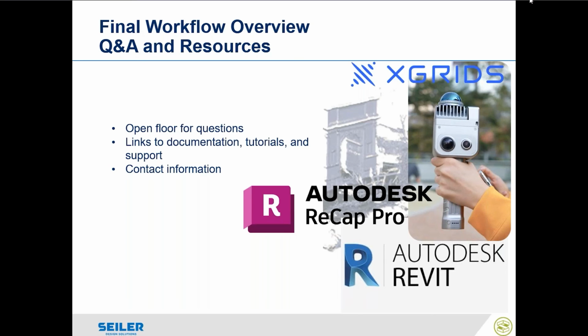Now the software is set up to remove those transient objects when you're processing. So as the slam scanning is going through, as you're seeing people in the raw data, when you get to the process, most of them will be removed. You can dial it down, so there's like a narrow tunnel. Let's say I'm putting this through a manhole or a smaller tunnel. There is an algorithm that brings that bubble back into 0.5 meter. I think you could dial it in less or not; I would have to check on that. So it's going to be a meter by default, 0.5 meter for confined spaces.